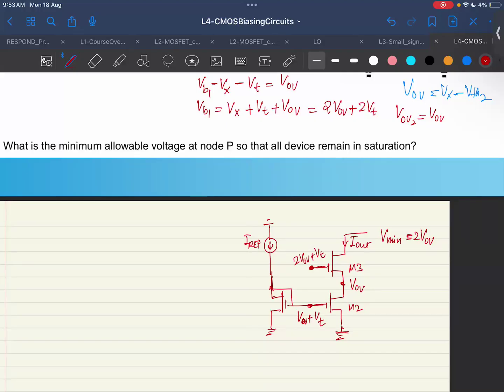One thing is clear, that I cannot have two diode connected generating this voltage. That is not going to work. So because I have this IREF, with copies available, is there a possibility to use this IREF to generate this voltage? And this is not in the same branch, right? So I would use a separate branch.